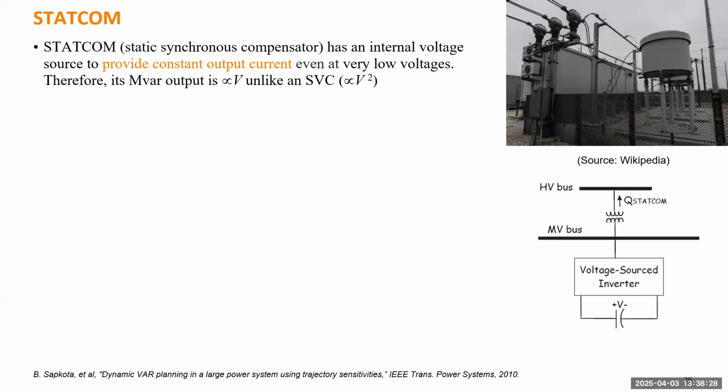The design can be very simple. Basically, a DC source tries to provide constant current, and through the inverter from DC to AC, it will just inject reactive power. So if you only look at this figure, it's pretty much like an inverter-based resource. This design is very similar to most solar farms and wind farms.